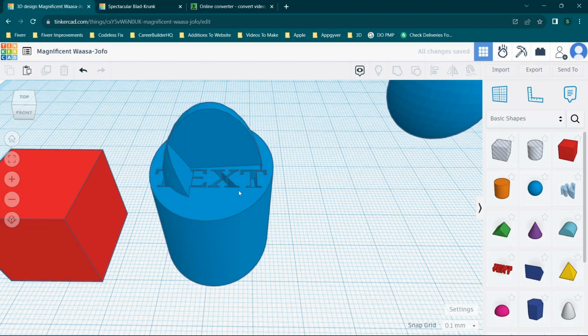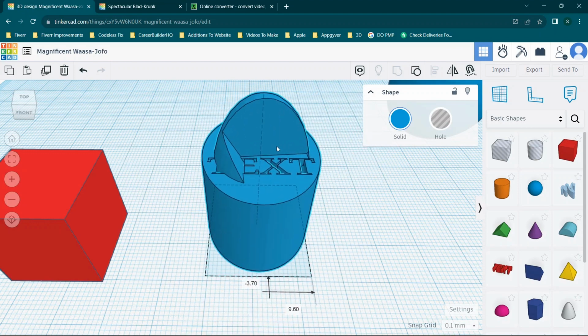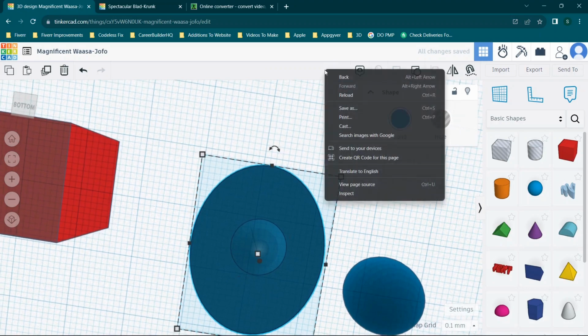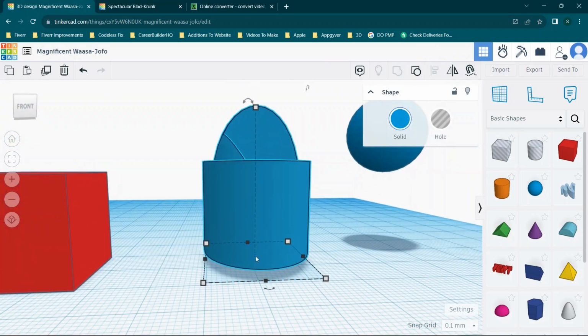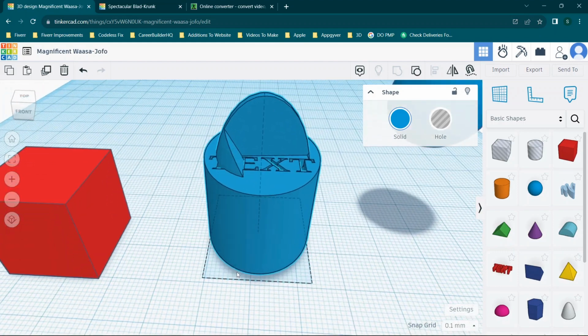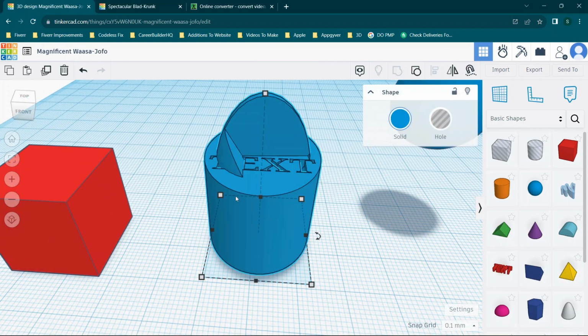And then you'll see now, because the objects are inside of each other, we now have one single object, and it's those two objects combined. And you'll see it comes out just a bit on the bottom. So this is basically what this new shape looks like. Now, if you wanted to, you can again choose the different work planes to line up with this object, but that'll show you how to basically combine simple objects to make something more complex.